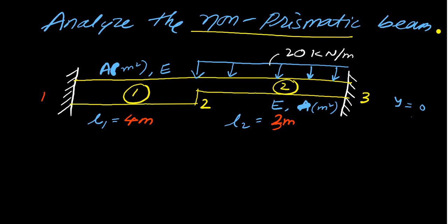Okay, so first, as you know, for a beam element we have to calculate the element stiffness matrix. That value for both the members, then we are going to add in the global stiffness matrix. First, I am going to write the general formula of the element stiffness matrix, that is K is equal to EI by L cube. Again there will be a 4 by 4 matrix.